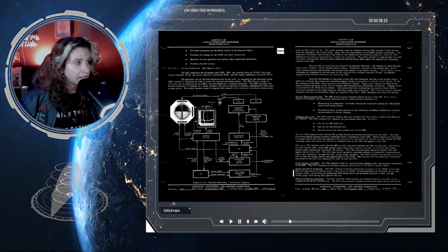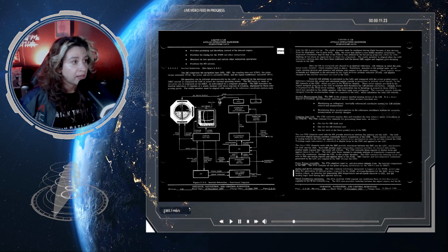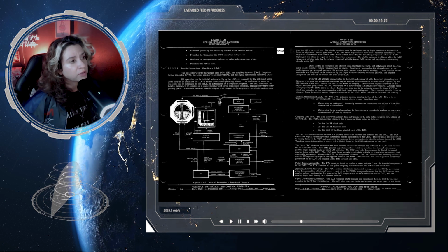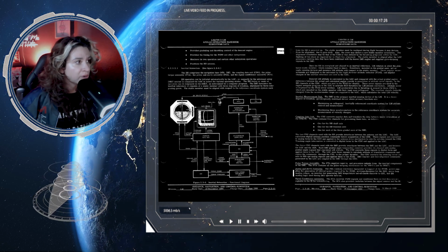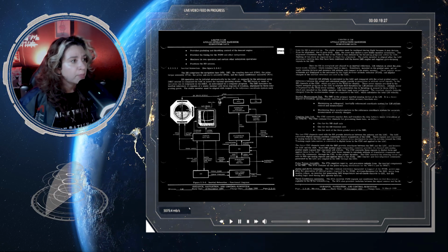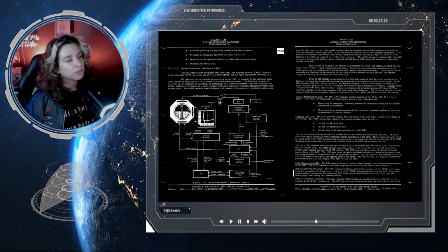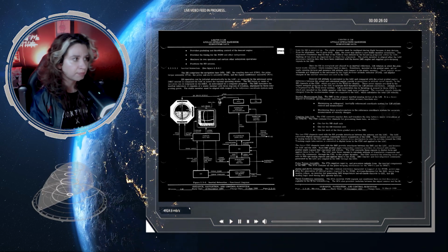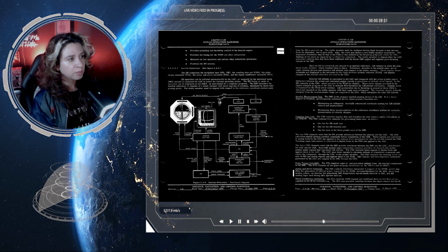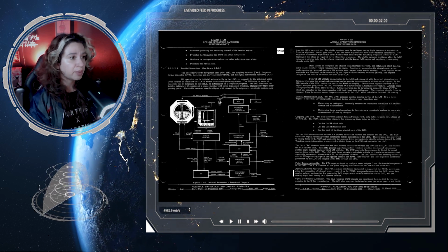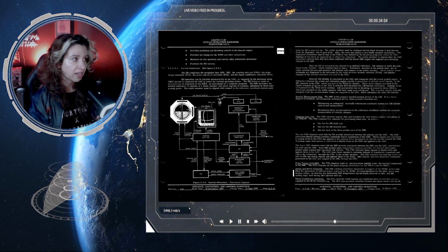The ISS comprises the navigation base, the NB, the IMU, the coupling data unit, or the CDU, the pulse torque assembly, the PTA, the power and servo assembly, the PSA, and the signal conditioner assembly, which is the SCA. ISS operations can be initiated automatically by the LGC or manually by the astronaut using the DSKY.